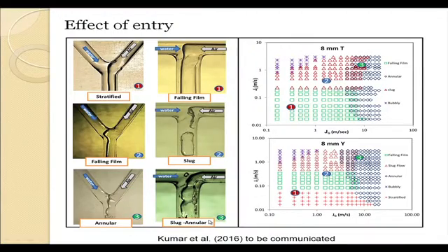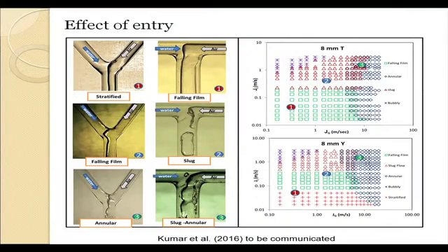So, what we did, we performed some experiments with air and water in downflow for the entire range of mini channels extending from 2 millimeters to 12 millimeters, and we used different angles of the injection nozzle. We injected water and air from diametrically opposite points across a T junction, and then we subsequently performed experiments by varying the angle between the two arms.